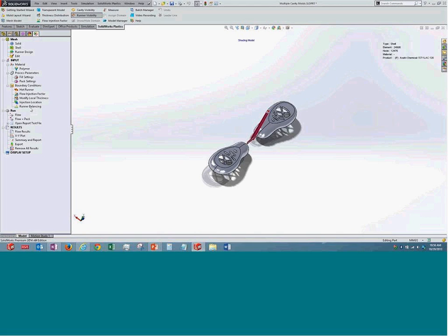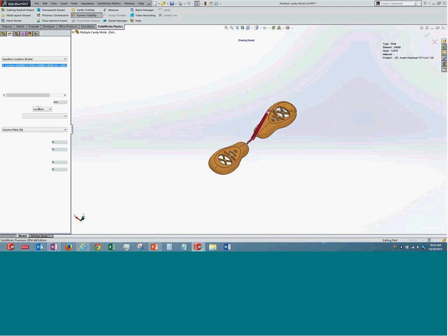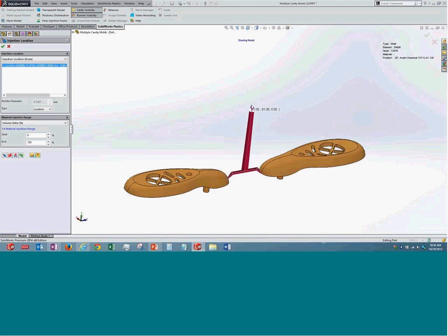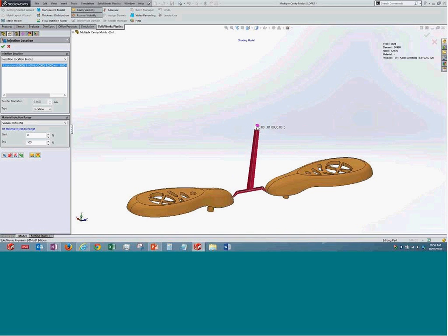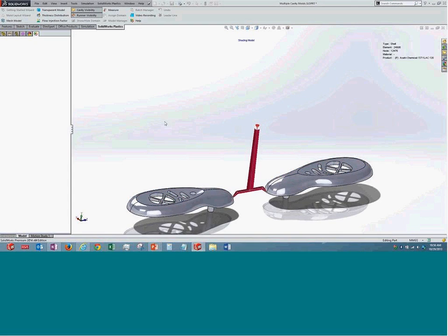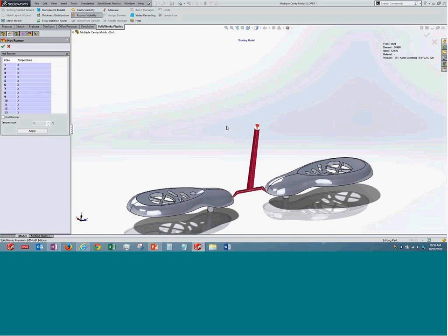And finally, there is a new option which you will see as hot runner. If you want to maintain runners as hot runners, then you just select them, first of all say they are hot runners, and specify the temperature at which you want to maintain them. So if there are any hot runners, you can use this option. The rest remains the same, no changes. Flow result, it's like this.